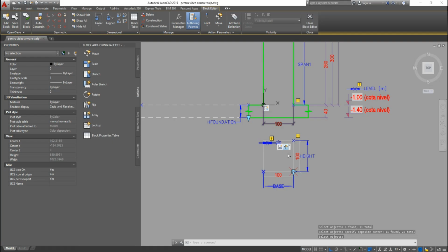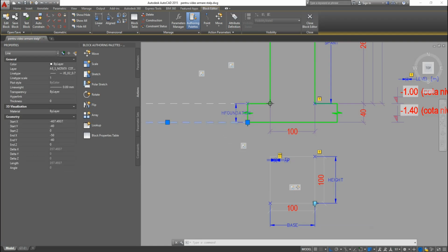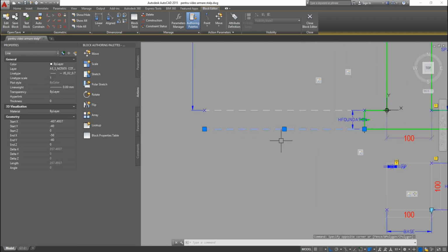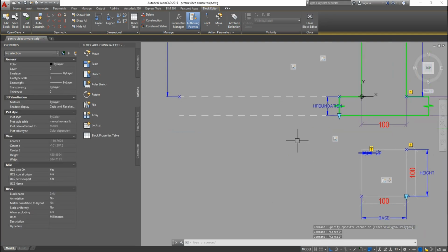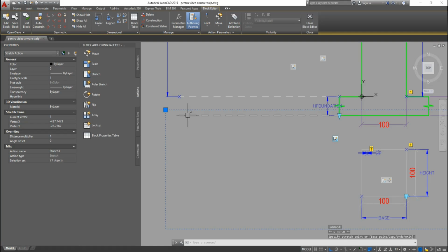But we are now coming back and we want to include this line also in its entirety. So it's a great occasion to show you how we can do that. We're pinching the action again, and we're just going to take this time the grip defining one corner of the area, extended. So now the whole line is inside, and check again with double click, action, modify, hit enter.